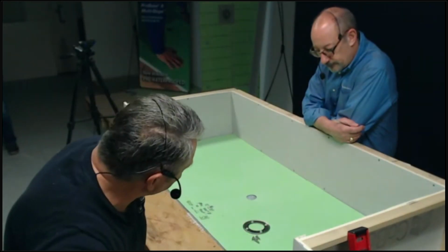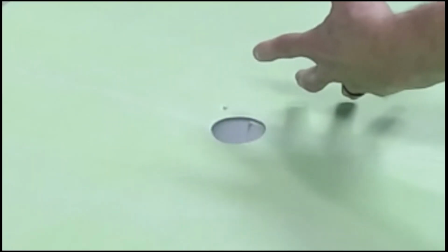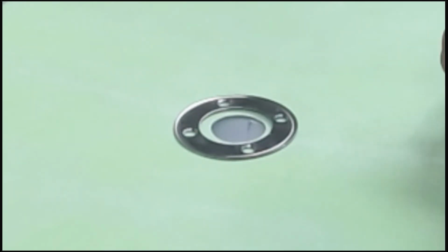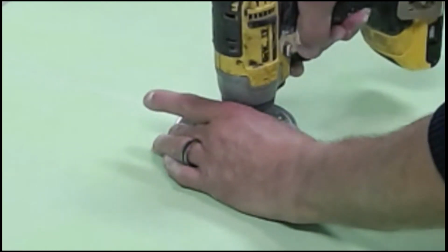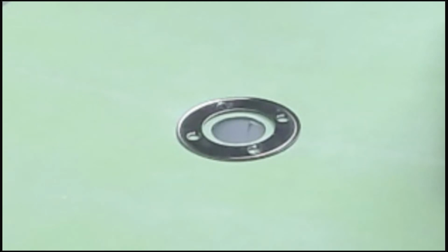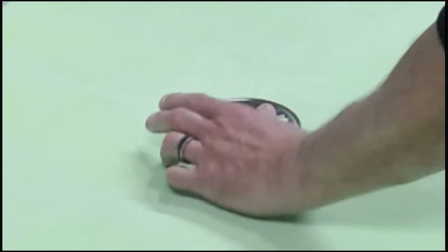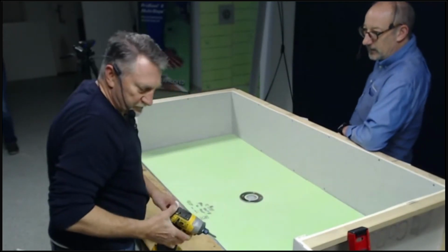Take our clamping ring. Identify where the holes are for your screws. You can feel it, or if you wanted to leave the screws in and then cut them out like you would a pan liner, that's fine too. So I found where my first screw is. If you use an impact, just be careful you don't over tighten. Get my second one in. I just snugged them down tight. These other two, the screw will just pop right through the membrane. With movement or anything like that, you don't worry about that membrane shearing loose, it's mechanically connected in there.